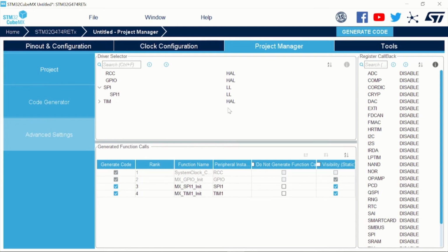It takes fewer clock cycles of the microcontroller to execute the commands. So this is very important for digital power applications. I would suggest we start with the HAL layer to have a better understanding. Then as we gain more understanding of the STM32CubeMX tool and the firmware, we can select the lower level libraries and optimize the code, and accordingly we can see the difference.